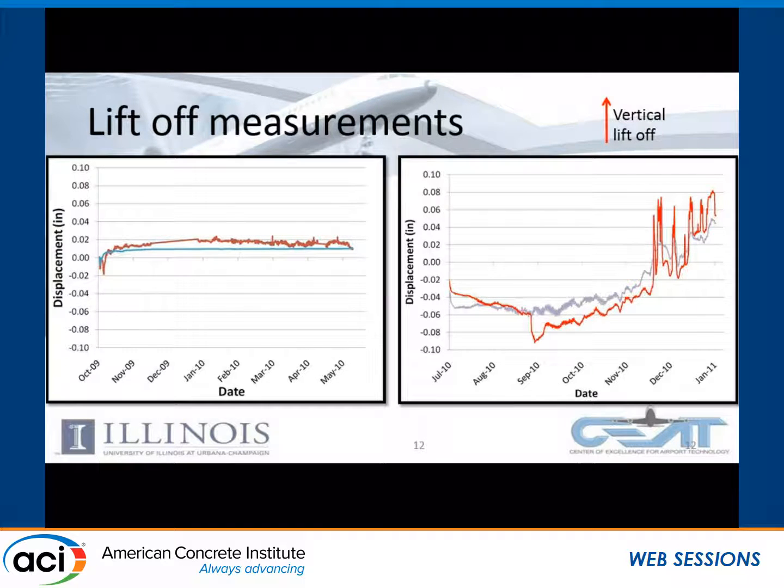We had a little bit more movement where previously the movement was like 0.003 at a maximum. At the gate we had 0.02. So there was definitely a difference. The pavements are constructed in the same manner. But once it got up to that level, there was very little variation. This makes sense. The pavements are all doweled together, so they act together. So the movement wasn't as great.